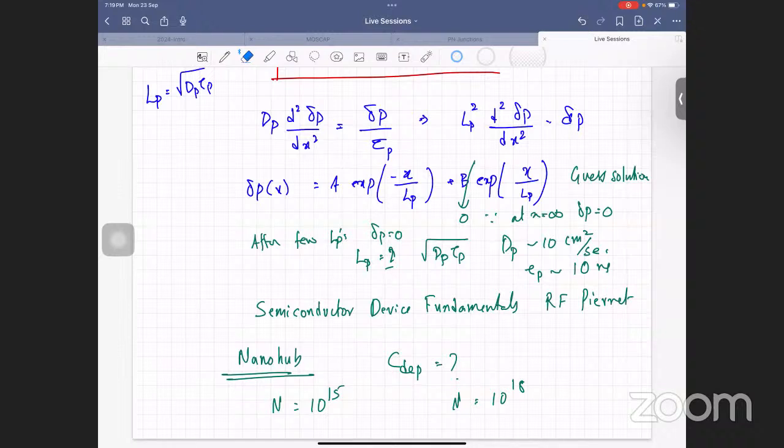It cannot be P-type. Can somebody flash that assignment, please? When we say PMOS, we're talking of N-type doping. Yes, sir, that's the confusion I'm having. So NMOS, P-type substrate. One of the TAs can flash that for me, please? Assignment 7. Yes, it's a PMOS. Then if we are increasing the doping concentration, how will the threshold voltage change? It's a PMOS device, so it should be N-type doping, right? But it says acceptor doping.